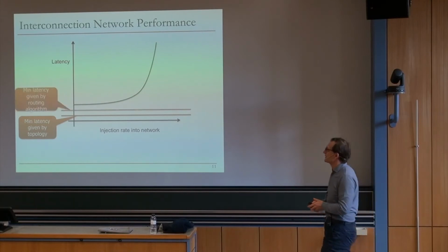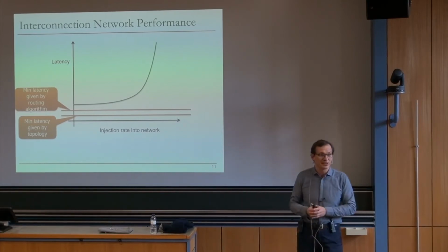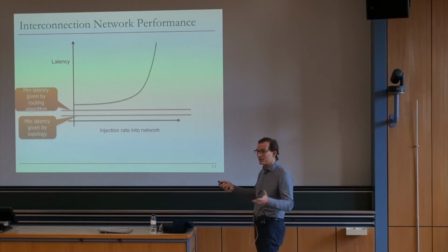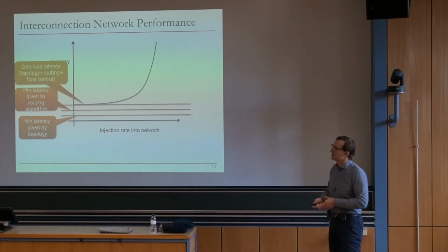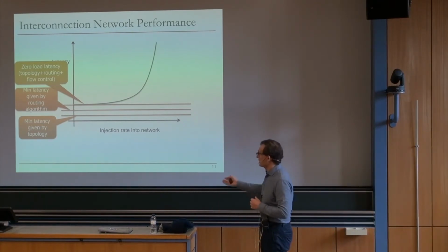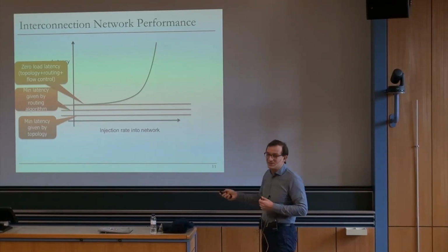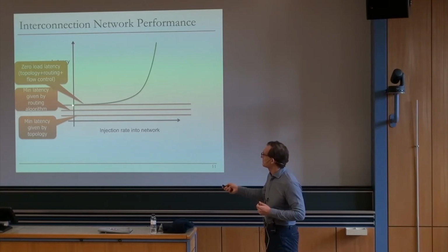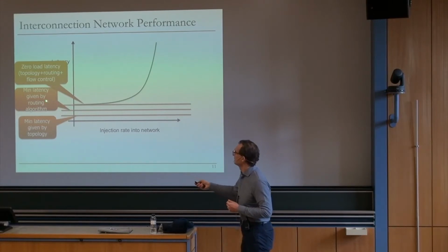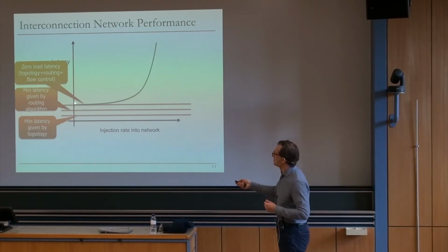And on top of that, there is some inefficiency because of your routing algorithm, because you don't necessarily do a good job in routing, or there's some latency in routing, fundamentally, that affects your minimum latency. So the routing algorithm affects that. And on top of that, there are flow control mechanisms, just like we've discussed. All of the buffering overheads, or the management overheads of the flow, add to your minimum latency. As a result, you get to this point. So topology, routing algorithm, and flow control all together get you to a point over here. Okay, so that's your zero load latency.